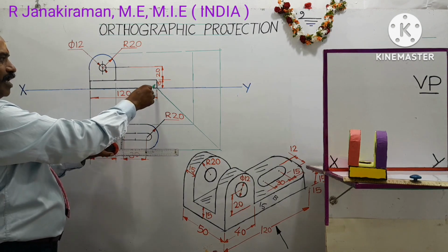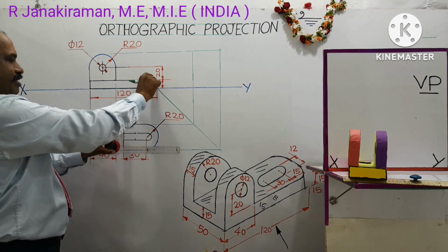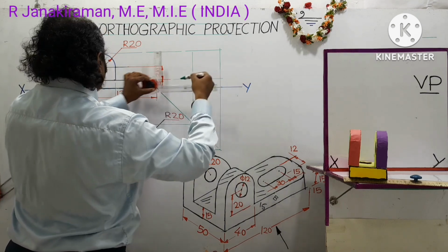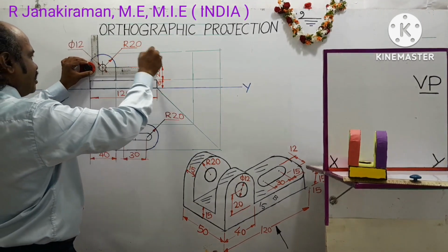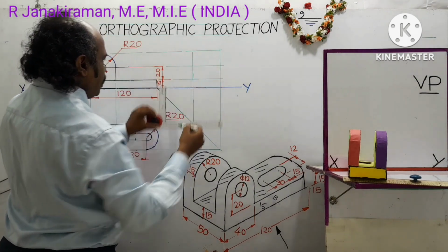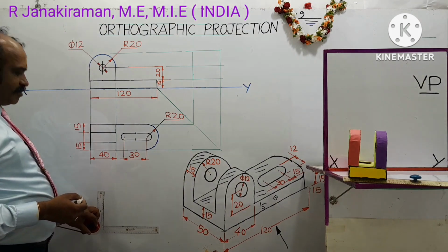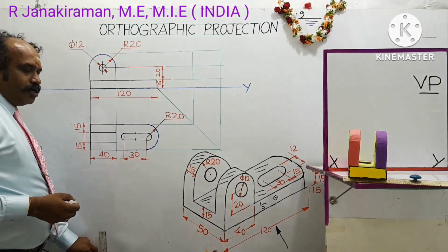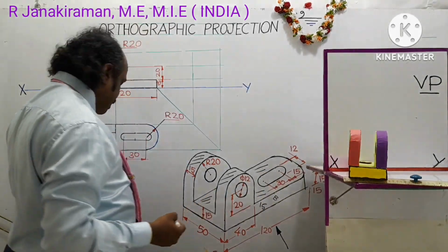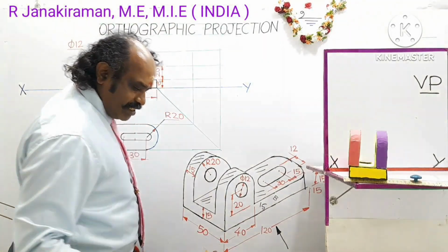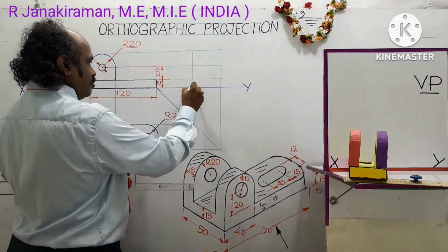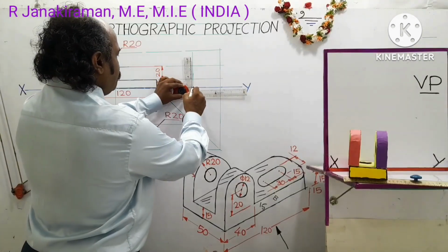Along this base breadth, which is the height of the base, draw a projection line like this. Also, you project the center of the circle. Okay. So next, this will be the breadth of the base, shown yellow in color. Using an HB pencil, draw various lines, edges. This smaller rectangle is this portion. You draw it using an HB pencil.